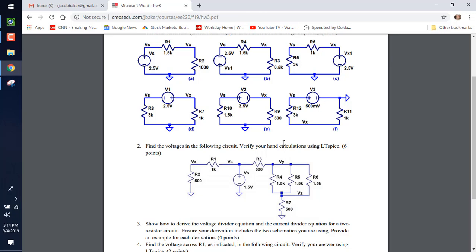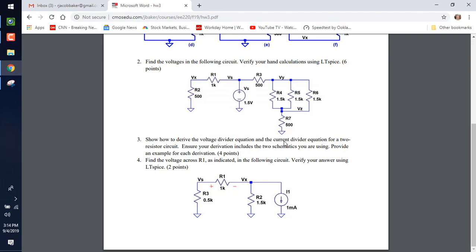Let's go to a harder one. Well, not really. Okay, here's number 2. What's the three 1.5Ks in series? Okay, what did I tell you? And I did this today in lab this morning. I did a digital to analog converter, and we were going through and combining resistors of like value, and I had lots of students in there that took circuits with me, and they were like, ugh. So when you have like resistors in parallel, what do you do? Divide.